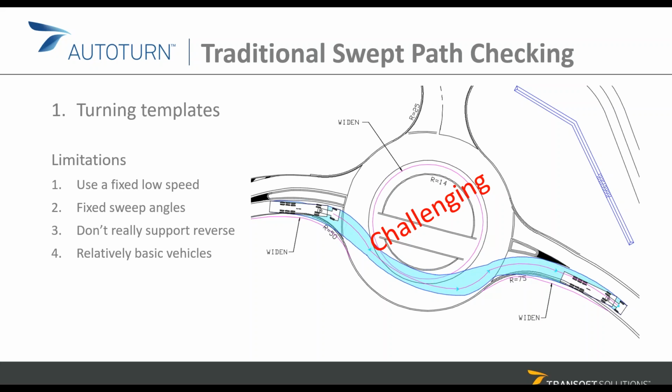The other key element we should mention at this point is that vehicles in a design guideline, because they're design vehicles, are intended to represent most vehicles using that road infrastructure. Therefore, for more advanced vehicles such as wind blade trailers or super long trailers that have rear steerable axles, you won't find turning templates.